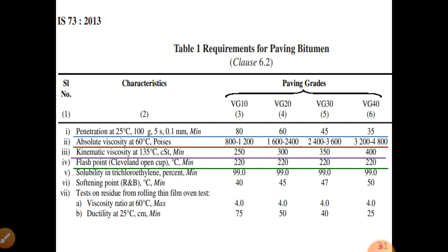Flash point measured in open cup, minimum 220 degrees centigrade. All viscosity grades have minimum flash point 220 degrees Celsius.